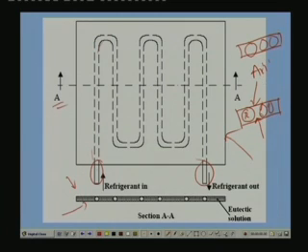So there is a gap between the tube and the plate, all this space. That space is normally filled with a eutectic solution. Eutectic solution means a solution which has low freezing point, right? So when you fill this space with the eutectic solution, there is a good thermal contact between the refrigerant tube and the outer plate, because the eutectic solution, which is a liquid, has a high thermal conductivity compared to air or vacuum. So as a result you get good performance.